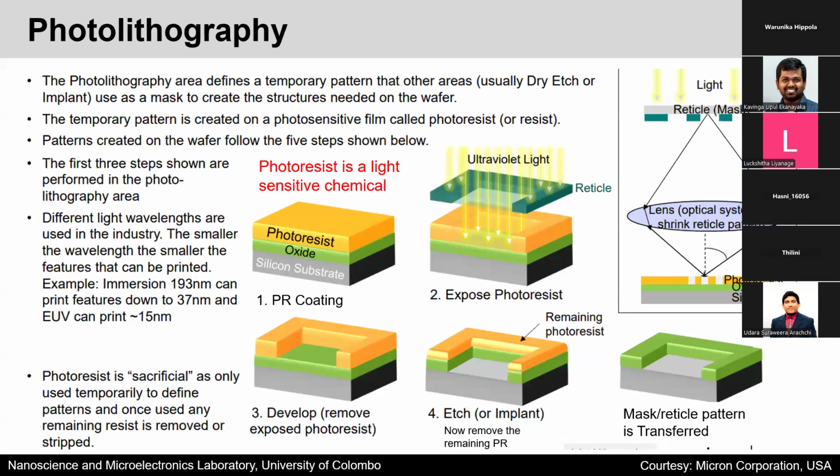Photolithography is used to define a particular pattern onto the chip, right? Let's say you have a silicon and silicon dioxide wafer, and you have grown the oxide already. You apply the photoresist, which is a particular liquid. You apply the resist, and then you spin the wafer, and the resist is equally coated throughout the wafer. It has a very consistent thickness throughout the wafer, right?